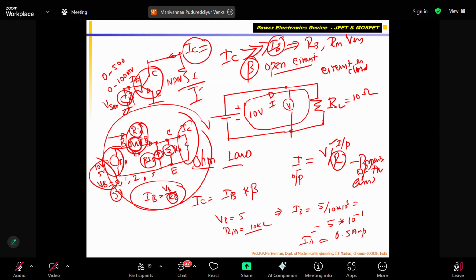Your car has some internal transistor amplifiers, and Chennai temperature is very high. If you go to Ooty, it is 10 degrees. Chennai is 38 degrees. Gain will change. Your control will not work properly. That's why they invented the op-amp and also gave negative feedback, which eliminates the open loop gain. AOL is automatically removed because of feedback gain controls.